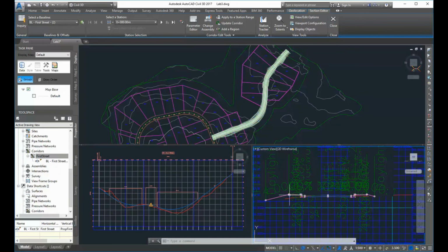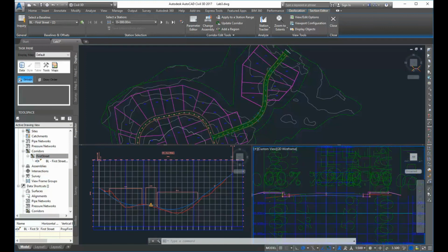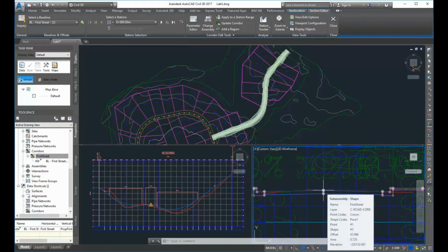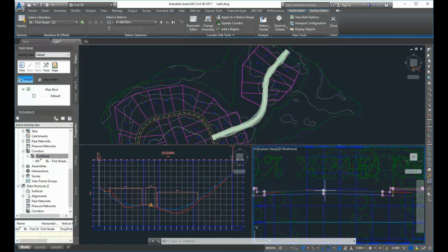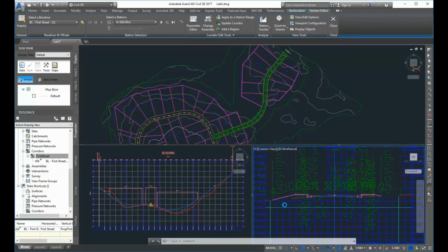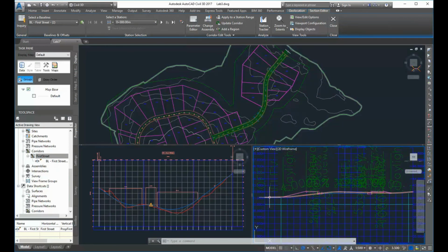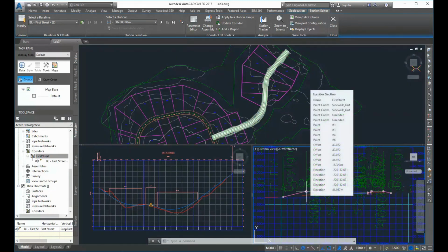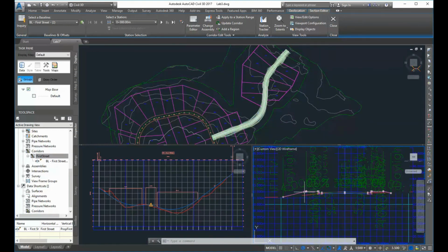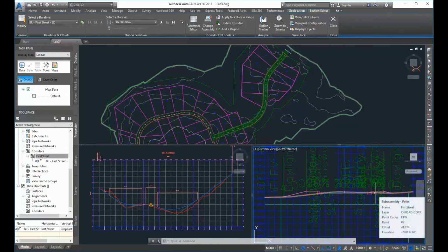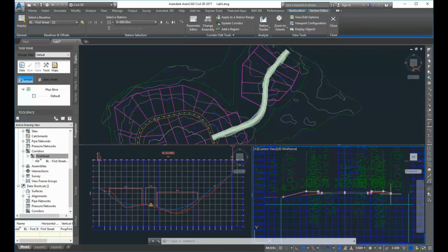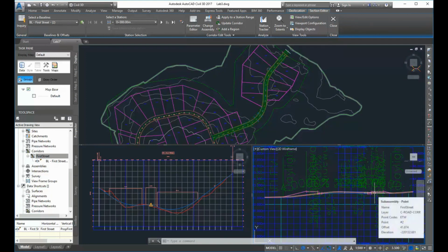I'm matched right here at, because remember by definition we said that we were going to begin the vertical profile right at existing ground. But this red line is showing the existing ground, and anyway, it's sloping. The ground is sort of sloping away, so by the time I get to the back of the sidewalk, the back of the sidewalk is up in the air, so I have a fill slope. And remember, it's going to go at 4 to 1 until it matches. And the same thing here, if I kind of highlight on that red, that existing ground, there's a little bit of fill. That back of sidewalk is going to be a little bit higher than the ground.